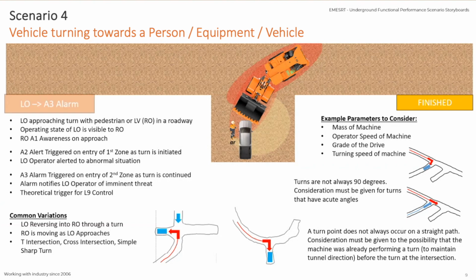I've seen plenty of operations that have required a multi-point turn to actually traverse a full turn because of the sharp corner. They do exist. They're not as common as the other examples, but nonetheless, they're there. So we need to consider those really acute angles as part of our turn in our design process. And because we've got that acute angle, we also need to consider that when the traffic is going the opposite direction, it can actually transition to a merge rather than a stop and turn.